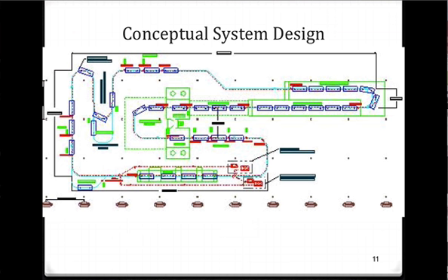Here's an example of a serpentine flow pattern that is arranged in a circular fashion. As you can see, we've got an overhead power and free conveyor, and the rectangles here represent carriers on the conveyor. This region here represents a loading area where we bring in our material loaded onto the carriers. It then moves through the power and free conveyor to our first process here, and then our second process, third process here, and fourth process. And then finally, we have a staging area here where we do some additional assembly. And then our final process here, leaving that, we go to an unload area here.